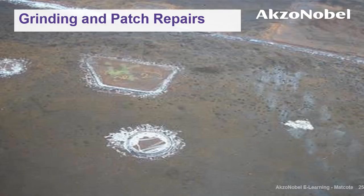It's also important to ensure that the blast itself is done with the right pressure and the right grit. On this slide you'll see a picture of a steel plate and the repairs undertaken to it. You'll also see that the repair area itself has been ground back to ensure there's no sharp areas and no weld spatter. And as previously mentioned, ensuring that the right blast is undertaken and the right cleanliness is achieved is key in the long-term performance of the system.